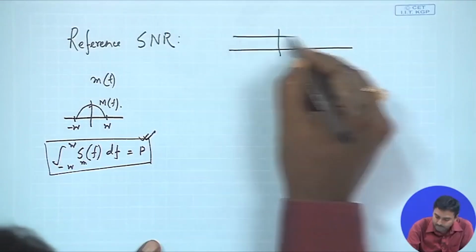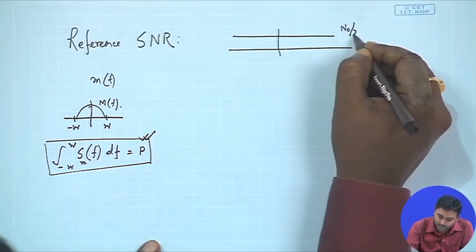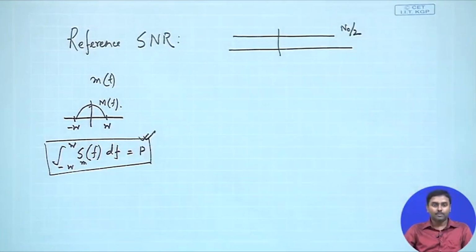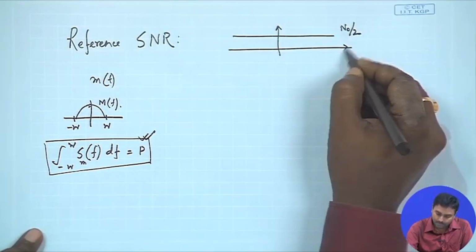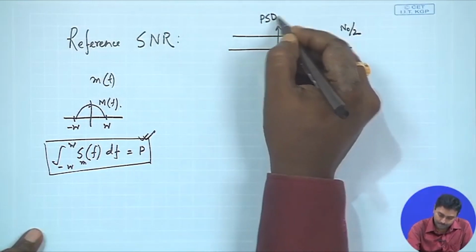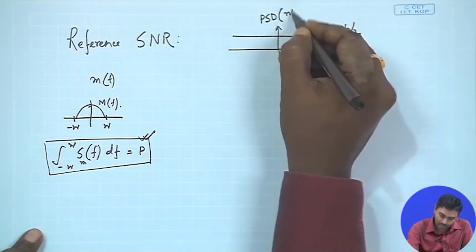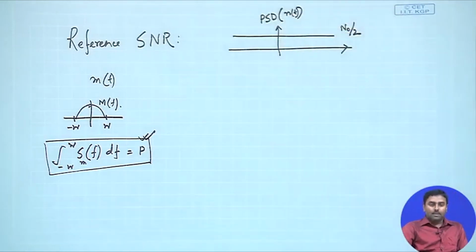And this corresponding signal is band limited. So, what we should employ, we have already talked about AWGN, additive white Gaussian noise. So, we will say that in the channel AWGN will be added. It is a white noise, so the spectrum is flat and it looks like this, with a strength N0 by 2. That is the power spectral density of the noise signal, let us say that is n(t).